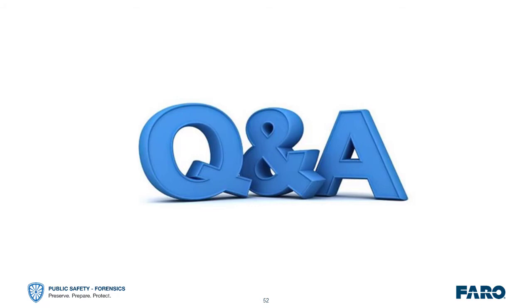Excellent. Good. Eric asked an interesting question as well. He asked, is a validation scale needed if my certification of my scanner is within calibration? Yes. We have to always put a validation scale in there because that's what the courts require, because it is a diagram for the purpose of measurements, and anything you're using for measurements needs to have a way to validate or verify that the measurements on that specific project is accurate. Even in your software, it will give you a standard deviation for that specific project.